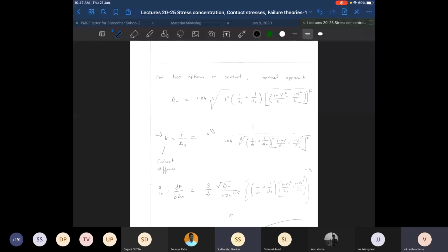Sir, do we decide the depth we need for the surface hardening using this analysis? Yes, this plays a very important role. Wherever the stresses are high, you want to harden the material. You're absolutely right. That was a very good insight from you.